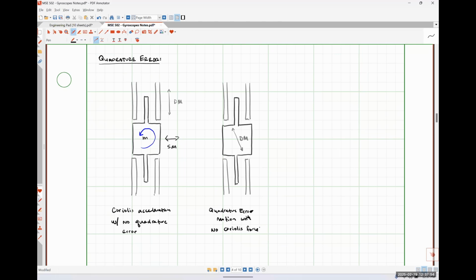I don't know how familiar you all are with things like laser trimming microstructures, but it's a pretty lengthy process where you're constantly having to measure the quality factor of the device while you're slowly removing material to tune it to a very specific frequency. It is a very lengthy and time-consuming process that would never be bothered for something commercially available because it would make the part just too expensive. Unless you're the US military and then you do that all the time.